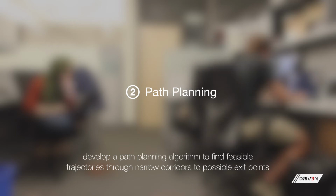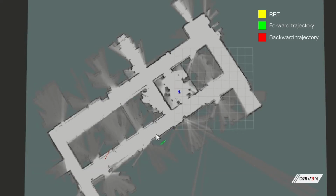Our next objective was to develop a path planning algorithm to generate feasible trajectories for reaching possible exit points. We chose a rapidly exploring random tree, or RRT, algorithm, visualized in yellow here, because of its ability to quickly plan paths in narrow environments. However, modifications to our RRT implementation were made to ensure the dynamics of the race car allowed for accurate execution.